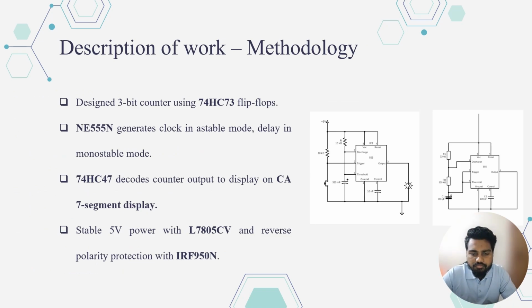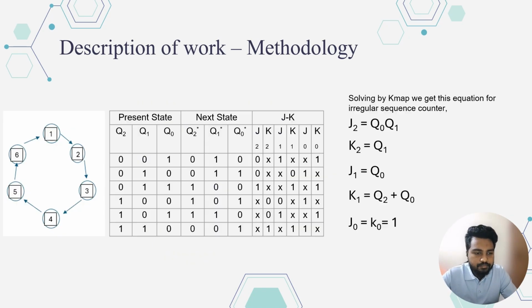The methodology involves careful integration of these components with the NE555 operating in both astable and monostable modes to handle timing functions. The counter output is efficiently decoded using the 74HC47 to display the final result on a common anode 7-segment display. This is the next state table that we got. This is all from my side. Thank you.